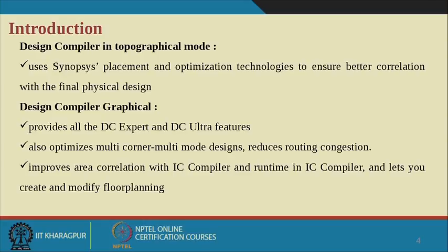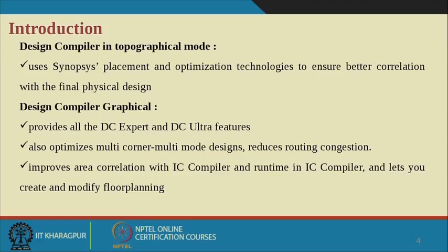So in design compiler, topographical mode is another mode. In the earlier part we have seen graphical. Here in topographical mode, it uses the Synopsys placement and optimization technology to ensure better correlation with the final physical design. So in the graphical mode we have seen that it is used for floor planning, and in topographical mode we can use placement for better correlation with the VLSI physical design.